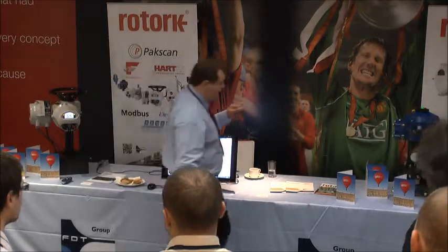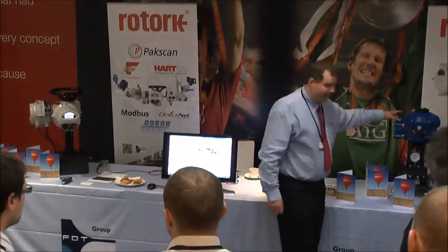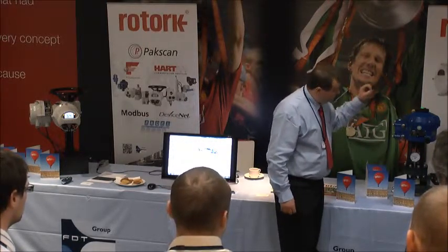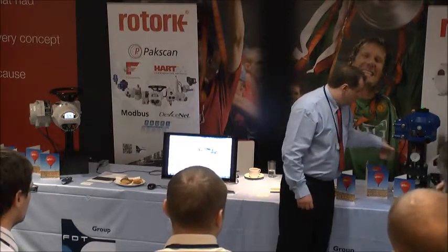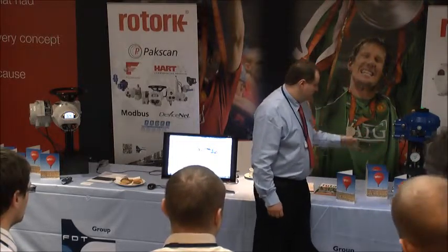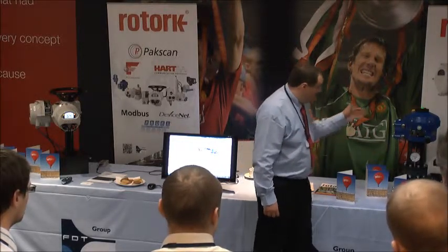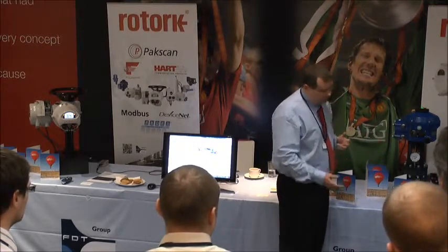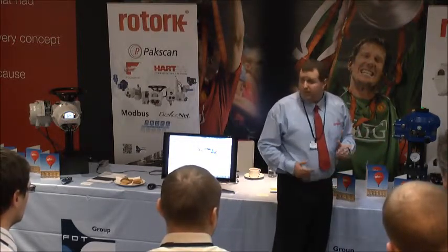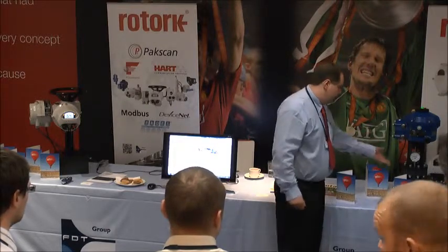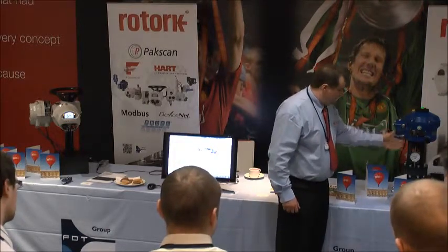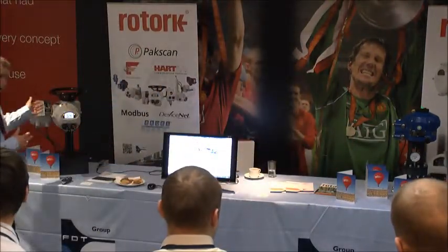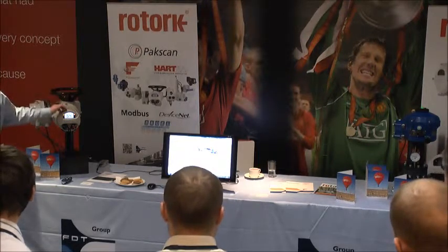This one is called CVA, which stands for Continuously Variable Actuator. This one would typically be used in process applications. You may find this feeding, say, feed gas or oxygen into a furnace, for example, and it would continually move up and down to regulate the flow, to provide the right air-fuel mixture or the right temperature, or the right flow of chemicals. So this can continually move all the time. And this other one would tend to be used more for open and close duty,